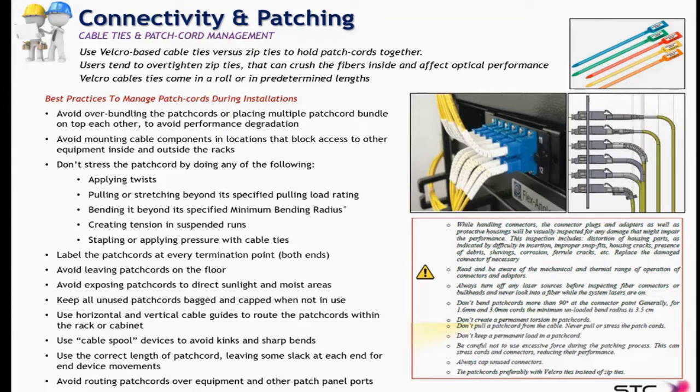Do not stretch the patch cords by twisting, pulling or stretching them beyond their specified pulling load, the maximum tensile load. Also, the minimum bending radius of the patch cords has to be respected. Creating tension in suspended runs is also stressing the patch cord, so it should be avoided. And stapling or applying any pressure with cable ties also creates patch cord stress.